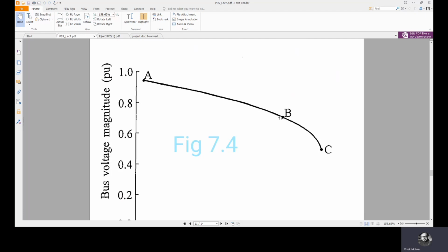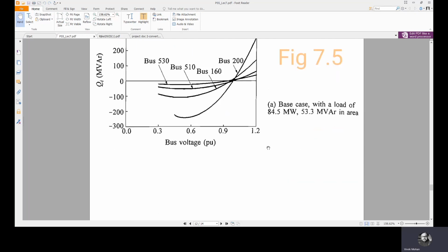In a way, it is active power transferred. Active power transferred in the sense that more active power is transferred through the line, which implies the I into X line drop will increase, which will cause a reduction in receiving end voltage. Drastic reduction in receiving end voltage for increased active power loading. So QV sensitivity is affected for an increase in P also. That is the point here.